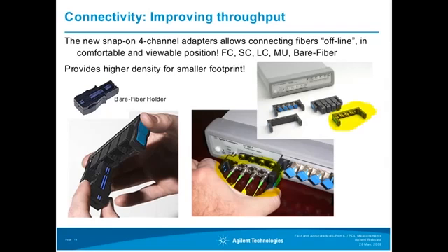So you just connect your device at a separate bench, and whenever the test system is available, you carry over this DUT with these adapters, and you can snap on these adapters in a very short time, much faster than if you were connecting the individual connectors.